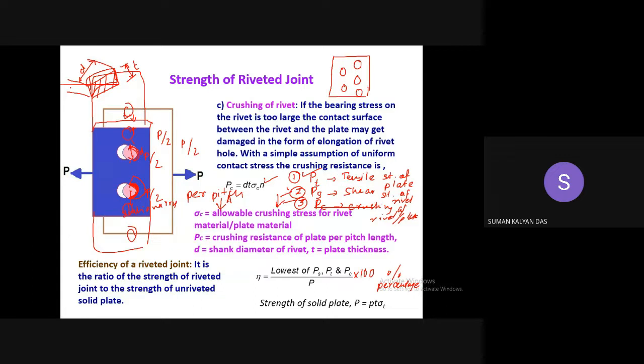Okay, suppose it is a simple lap joint, with a load on this side and a load on that side, okay? If you are dealing with this many rivets, no need to go for per pitch calculation. What Bhandari has done in the example, when dealing with this type of problem, is, as your friend was suggesting, directly take all 5 rivets together and equally share the load among all 5 rivets.